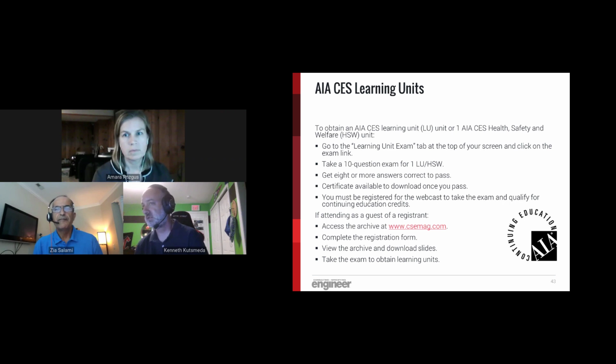Going back to your point, Ken, definitely on the downstream device we always see that overlapping, because one of the main reasons is that downstream devices are typically molded case circuit breakers, which do not have adjustable settings.